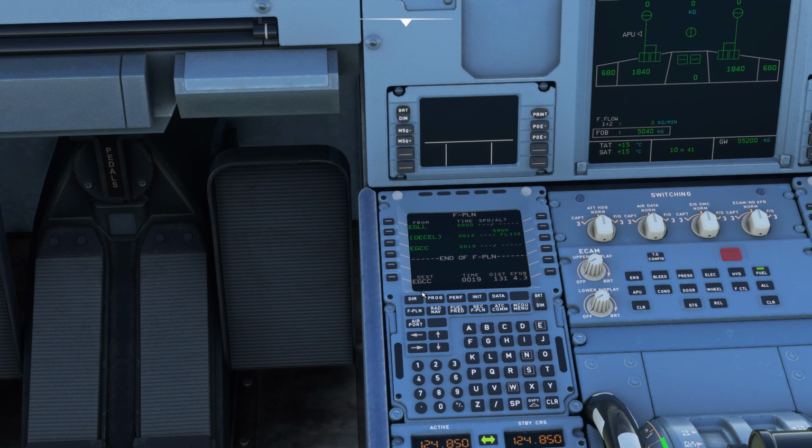So I'm going to start entering these, but first of all I'm going to enter the departure that I want from EGLL as well as the arrival to EGCC. The reason being that may put waypoints in that you already want to hit, and it will just skip a step if that's the case. So we'll click EGLL first of all, and then you click on departure. You need to select the runway you want to depart from, so I'm going to go from 27 right, and I want to take the UMLA 1 Foxtrot departure. So that's in there, no transition, and then just press insert. So you can see it's gone there: runway 27 right, UMLA 1 Foxtrot as the departure, no transition, and insert.